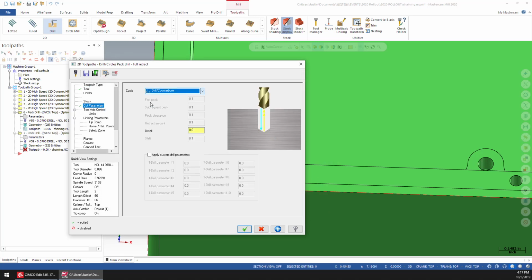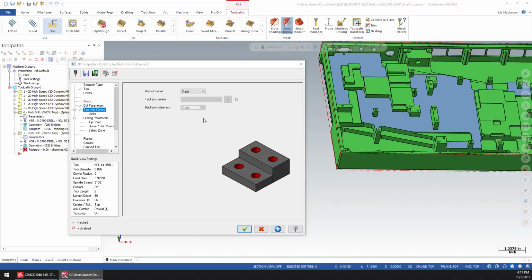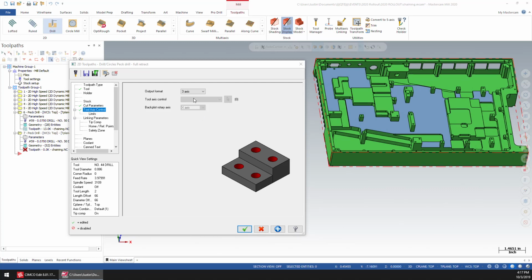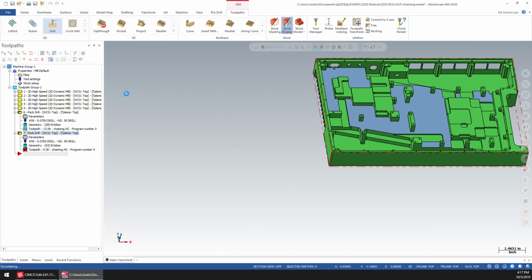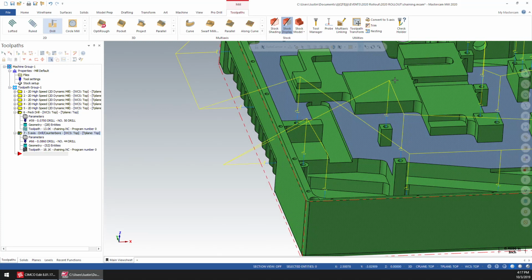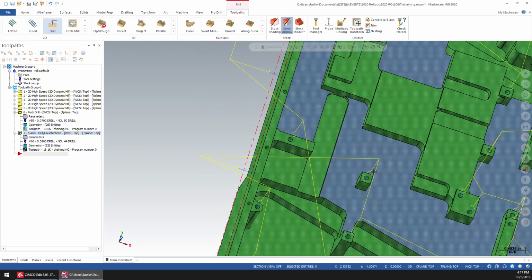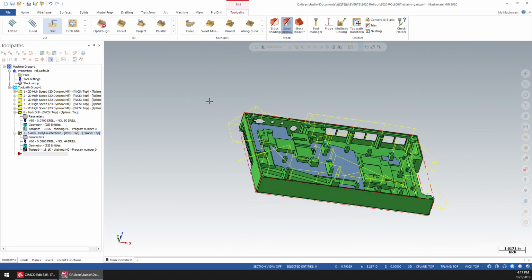So same thing. I'm just going to do standard drill for this, but now we're going to do this as a multi-axis. You could just say 4-axis, but since it's not going to require a 5th axis, I'm going to go ahead and just do 5-axis. We'll say we're good there. All of this is going to stay the same, and I'm going to green check this for now just to show you another feature. This move right here is a prime example. The movement from here to here drives straight through the part, and that's a no good thing.